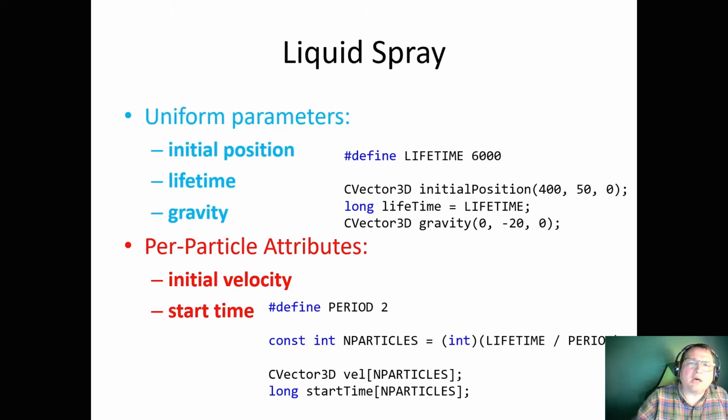The particles are reused, so after this 6 second cycle, we will be able to reuse the same particle again, and this means that we will never ever need more than 3,000 particles. These 3,000 particles will just be injected into the simulation at the pace of 500 per second, or 1 every 2 milliseconds.